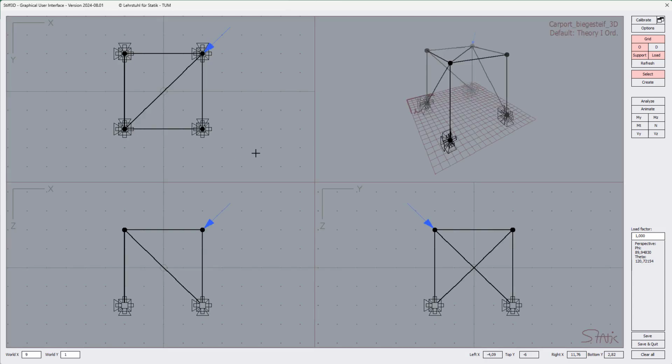You see already the basic idea of Stiff, that every one of the items what you see is context sensitive. That means if you just go with the mouse to any of the items, for instance here this node, pressing the left button, we can select it or deselect it, or the element, we're just pointing at it, pressing selection, deselecting it.